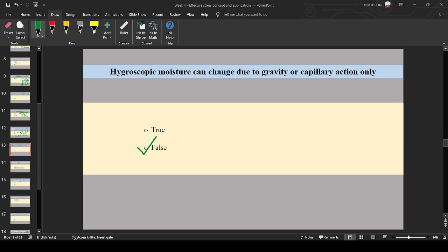This is the capillary suction zone. This is the groundwater. This is the ground level. So it is negative over here and positive over here. Positive means compressive, negative means tensile. So it is compressive below the water table and tensile above it. Neutral pressure means the pore pressure, that is U. Pore pressure is compressive below the water table and tensile above it.